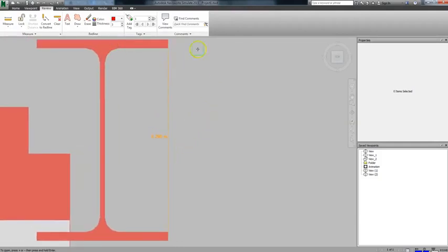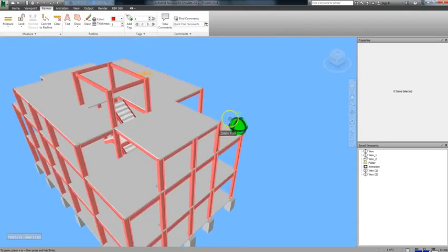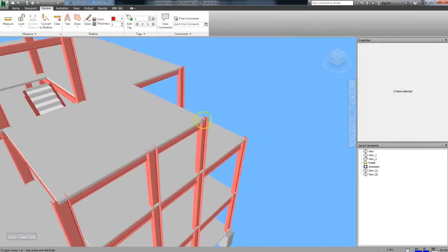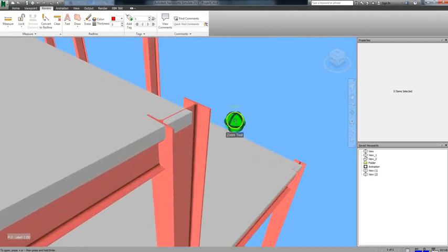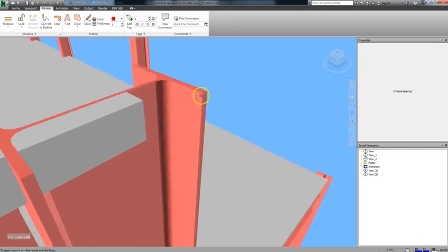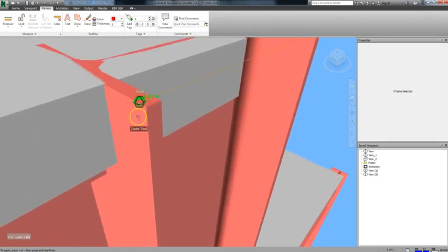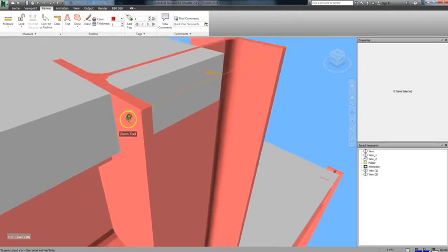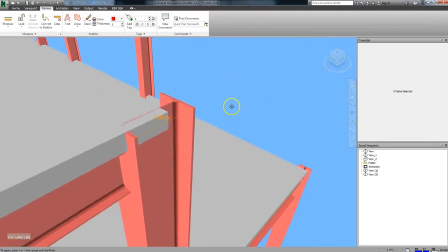Additionally, you can take measurements in 3D view as well. Just go to 3D view and zoom in wherever you want to start your measurement. Note too that it doesn't matter whether you're in perspective or orthographic view. The process for measuring in 3D view is exactly the same. Just be aware that because you're working with so many more dimensions, you have to be very, very precise. You may have to fiddle around for a little while until you get that X to appear, to show that you're exactly on the corner when you want to measure from one vertex to another.